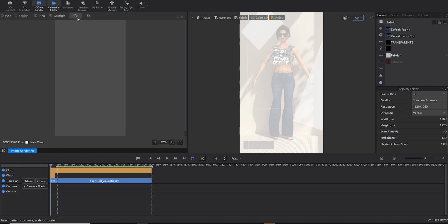And here I also need to adjust the device that's going to render it, whether it's your GPU or CPU. Lower the noise and adjust the render quality to fast, default, high quality, or you could just customize it. I usually select high quality and click on denoise, okay? Once you're done doing this, you are ready to render.